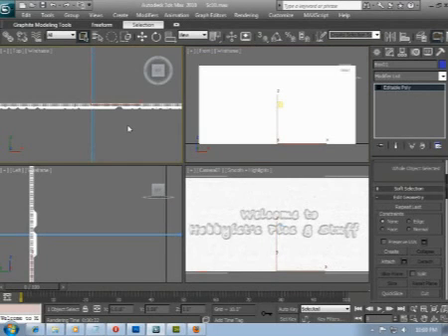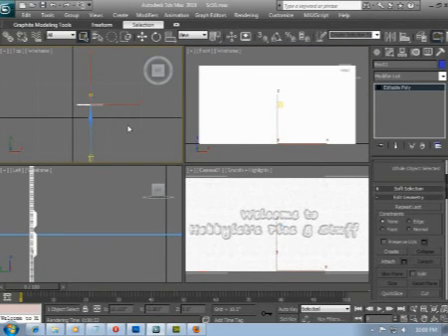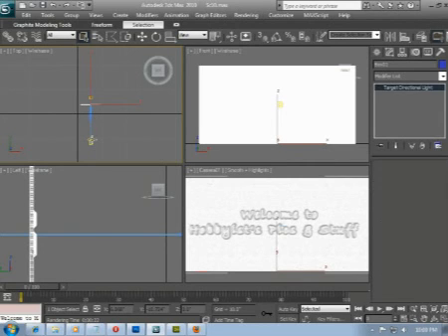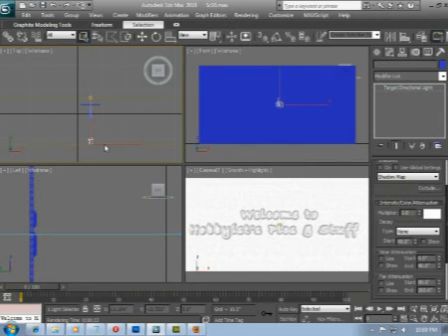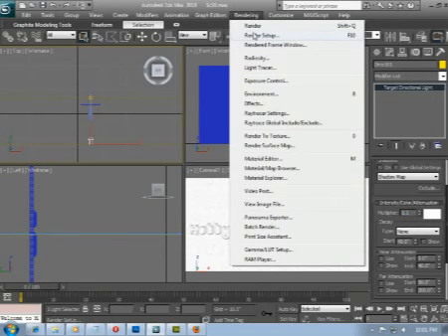Let's right-click in the top view and wheel out till we can see our light. And if we hit Q, we can make sure we don't move it. And then click right on the light. It's already on the Modify tab, and we opened the Intensity Color Attenuation area earlier. Let's move the multiplier value up to 1.1. You can see our text doesn't look so great in the camera view. And if we go to Rendering and Render,